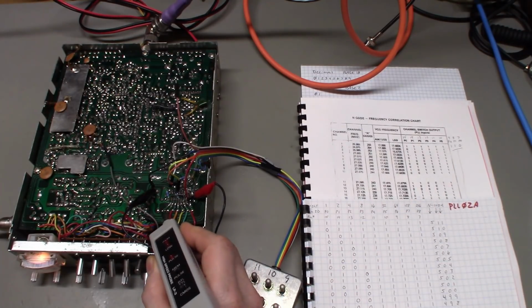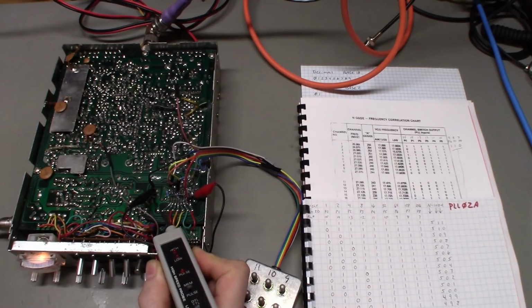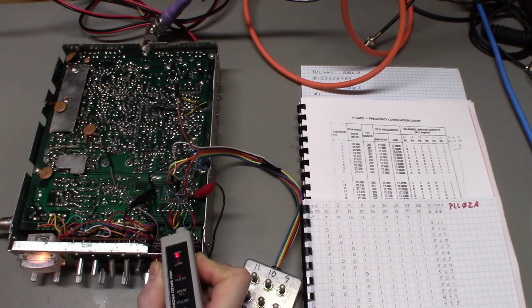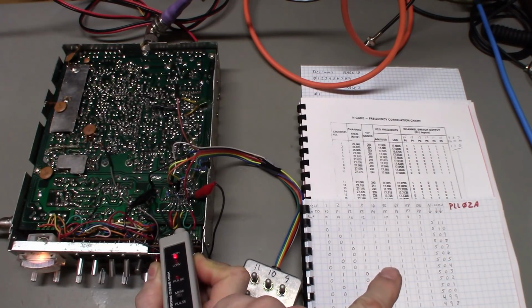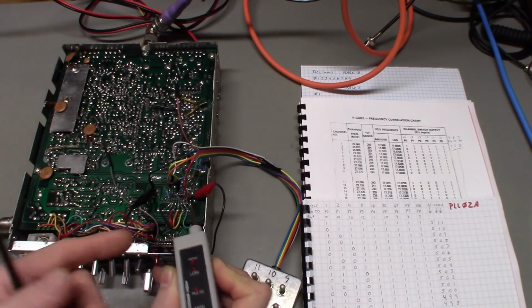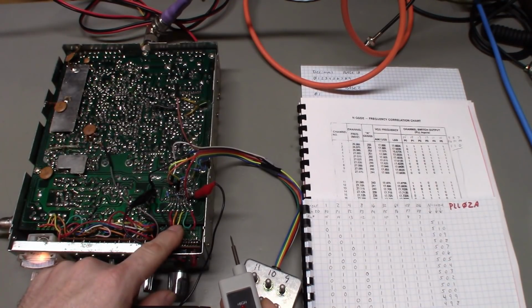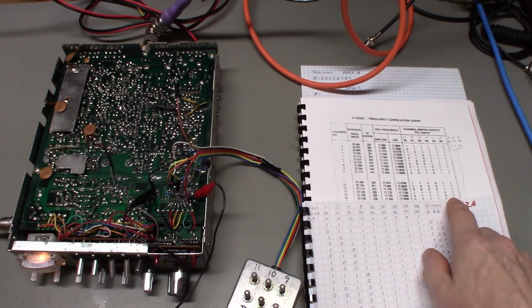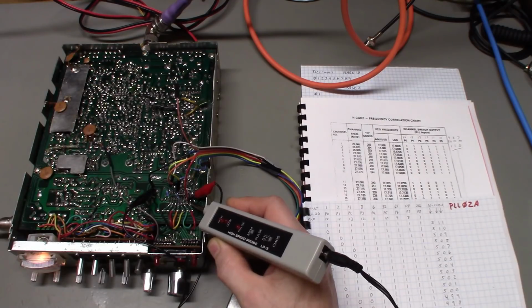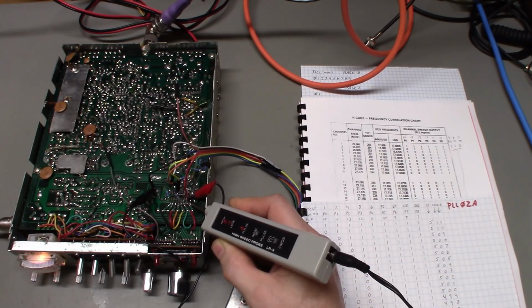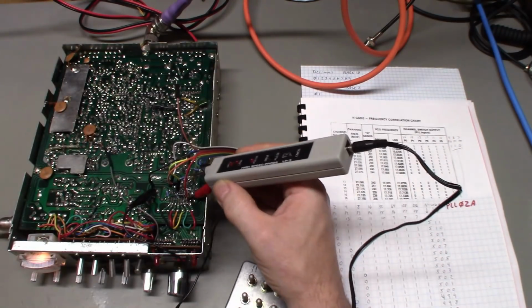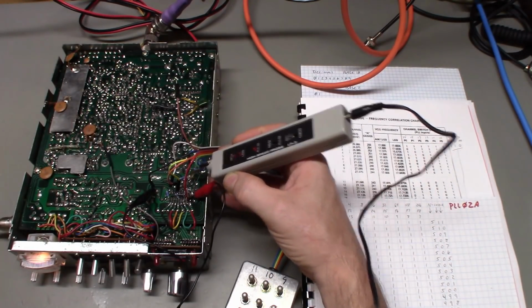So if I check, I should see 0 or a low, 0, 1, 1, and then we have 0, 1, 0, 1. So we know all the programming coming from the channel selector switch is correct. That was all these digits. These never change. This pin here, which is always high, okay, that's pin 9. Then we have pin 8 over here, which is always high.